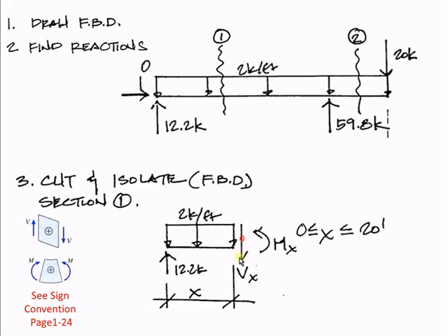Okay. Then same thing for our bending moment. So positive bending moment is, if you have a positive attitude, you'll be smiling, so you can see that this beam is acting in a way that appears that it's smiling. So that's a positive bending moment.